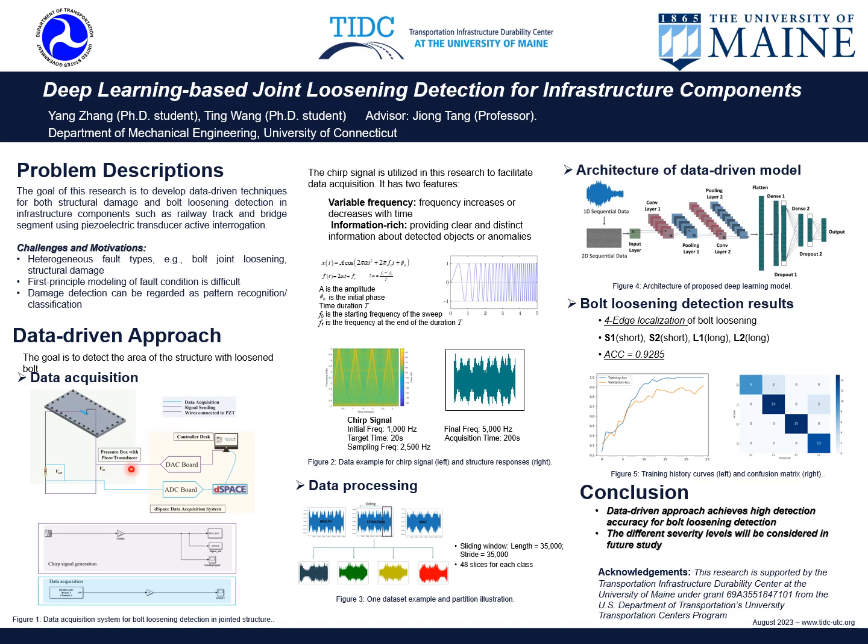As shown in this diagram, there are two plates fastened together using 32 bolts, with the piezo transducer attached to the top plate, and we use the dSPACE to realize the data acquisition. To classify which area has the damage, we divide these 32 bolts into 4 edges, these 2 short edges and these 2 long edges. The data acquisition is simulated based on a Simulink model.